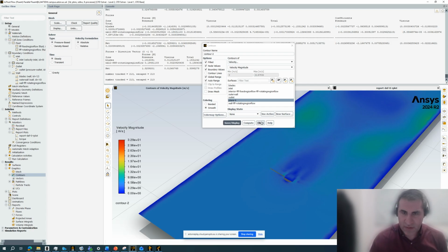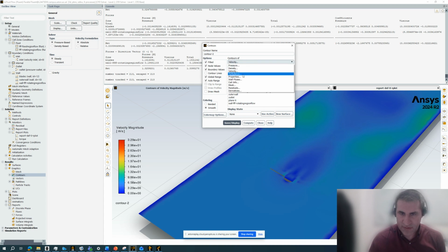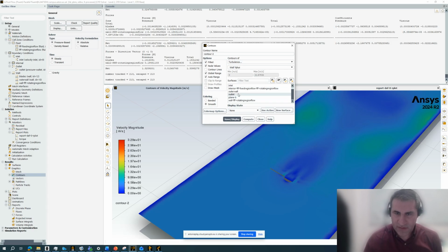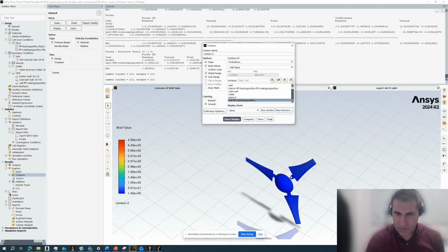One thing else that I would like to check is turbulence. For turbulence, we are always checking Y plus. What is Y plus? In theory, I will talk about that, but Y plus for this k-omega SST on the walls, these two, not global, and show on the local range.